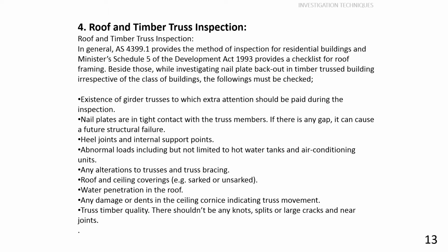Besides those, while investigating nail plate backout in a timber truss building, irrespective of the class of the building, the following must be checked. Existence of gutter trusses, to which extra attention should be paid during the inspection. Nail plates must be in tight contact with the truss members. If there is any gap, it can cause a future structural failure. Heel joints and internal support points must be checked. Any alteration to trusses and truss bracing must be checked.